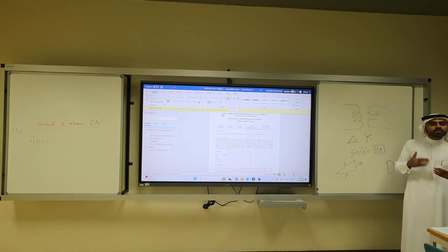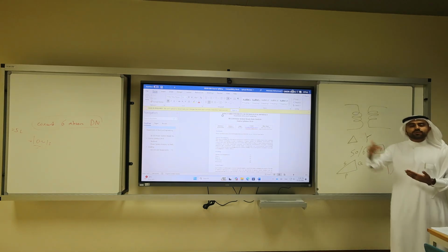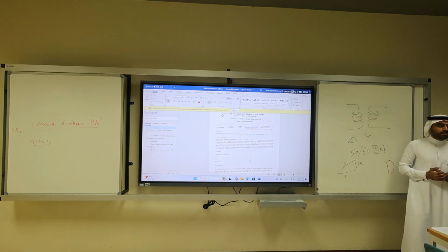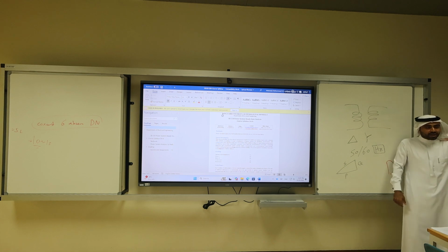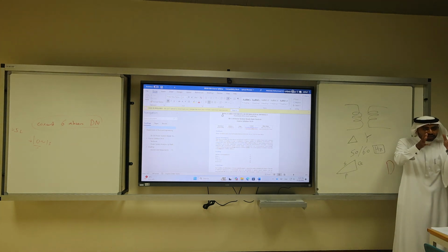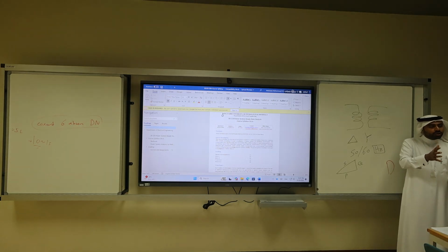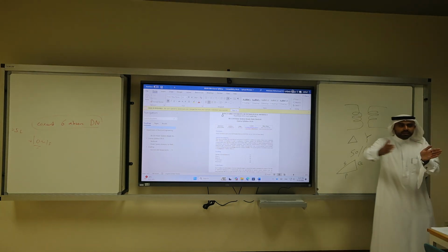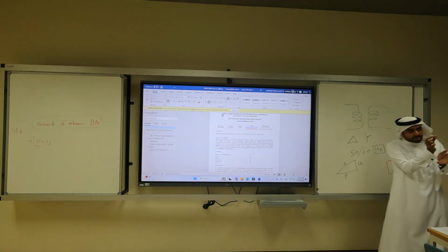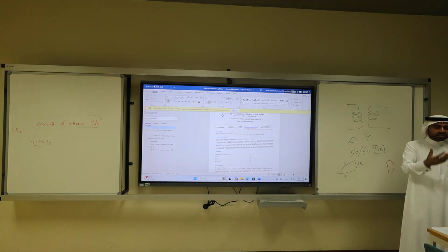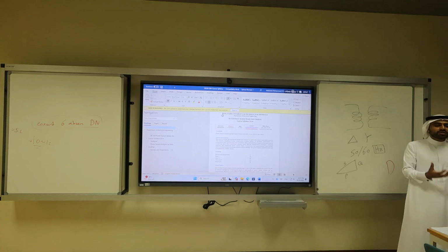Steady state means over a few cycles ahead. Not the exact cycle where we open the breaker. When we open the breaker, for example, this is transient. And to model the transient, we need computers that simulate the waveforms across small time steps. For example, we have real-time digital simulators.